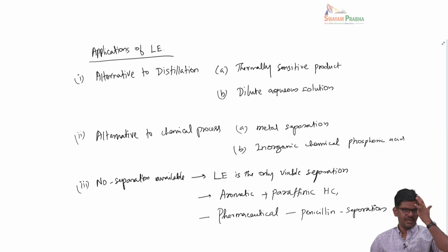So one important thing about liquid extraction is that I said there are three components involved minimum, and the two liquids, even though we say insoluble, still there is some amount of the solvent present in both phases. Okay, for example, in the acetic acid water system, I said even though the ester is rich in the top layer, it also will have some amount of water, and similarly the water rich layer will have some amount of the ethyl acetate also.